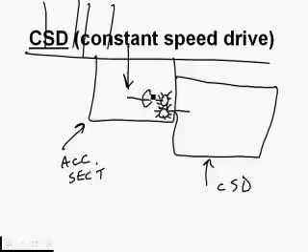So the engine is rotating, this gear spins, that gear spins, and this gear ends up spinning the hydraulic pump. But if something goes wrong with the CSD, this shaft in here, if let's say for instance the hydraulic pump seizes because it got too hot or it ran out of hydraulic fluid and had too much friction and it slowed down, then this shaft and this gear could bust up the gears inside of the accessory